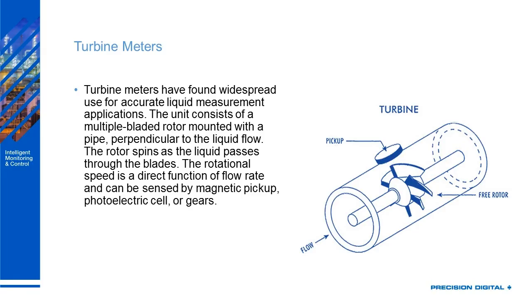You can apply that same type of concept to a turbine meter. Now a turbine meter isn't going to have the oval gears and isn't going to only allow material to pass through at a certain rate. However, the rotor inside of the turbine meter, the blades are going to spin at a certain rate as determined by how much liquid is being passed through. So as I use a pickup to sense the rotation of that rotor of the blades,